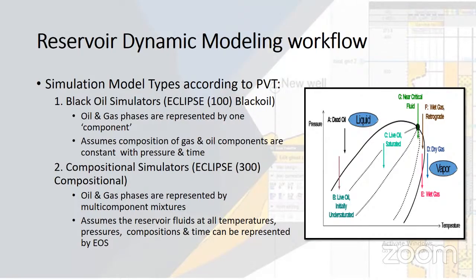For a gas condensate reservoir, we will use compositional simulation, with E300 software. For black oil, with an API of 24 or so, we will use the conventional black oil Eclipse, or E100. So the PVT will direct us to the type of simulation that you will use in running the dynamic simulation.